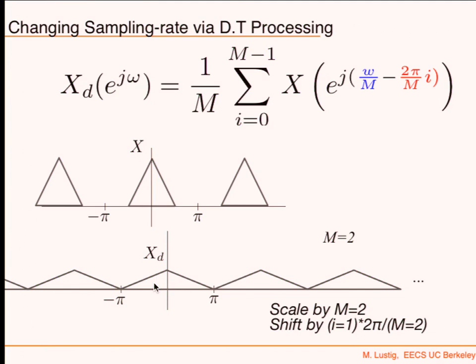Questions? This only applies to integer downsampling? Yes. Is this easily modifiable to work with fractional downsampling? We'll talk about fractional downsampling once we talk about upsampling. Why do we scale? The spectrum is scaled because of the 1/M. That comes out of the derivation. The truth is that if you sample at T times M, then you would have that scaling as well, right? Okay.